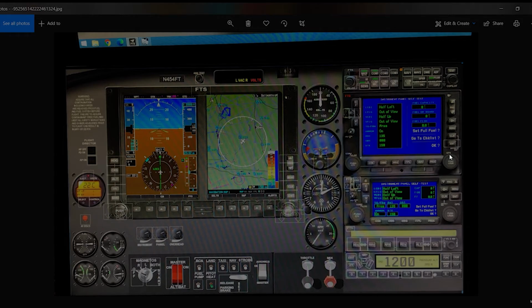Now, when you are using these buttons on the bottom, especially flight plan, procedure, or you're at the moving map display on the center, you will see little shaded or non-shaded rectangle boxes on the bottom. I know that sounds redundant saying rectangular boxes, but when you start using it, you'll notice these. You can cycle through those different boxes to get different menus and different views of maps and other things by using the top rotating knob, if I remember correctly. If it's not the top, it's the bottom. You have a 50-50 chance of getting that right.